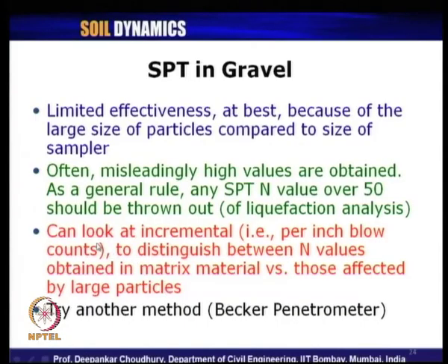And we should also look at the incremental, that is per inch blow, how many counts are coming, to distinguish between N values obtained in matrix material versus those affected by large particles.